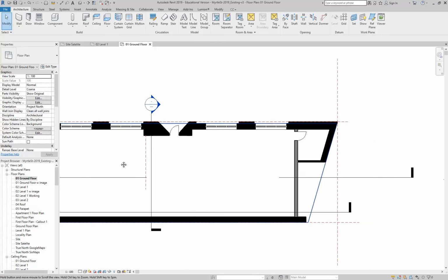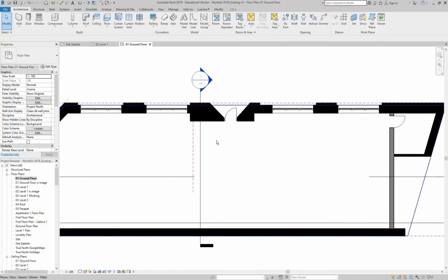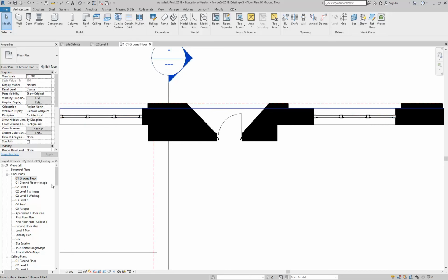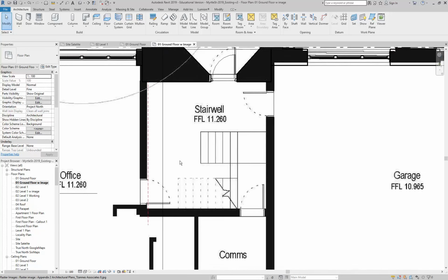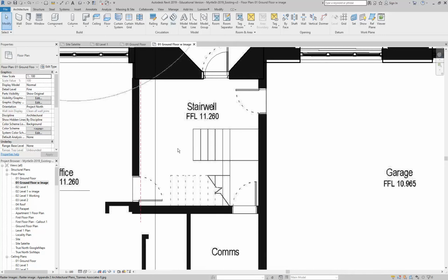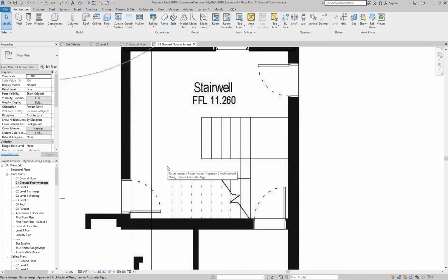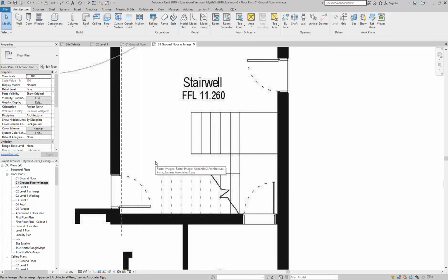Okay, so I just want to go over the stair tool and cover the main features, but then also have a look at some of the different things you can do to make different kinds of stairs. So I've gone to the view there where you can see that you've got the internal access stair shown in plan. And then, of course, you probably all know the stair tool lives on the architecture tab. You'll see in that circulation area you've got stair, ramp and railing together. And that makes sense.